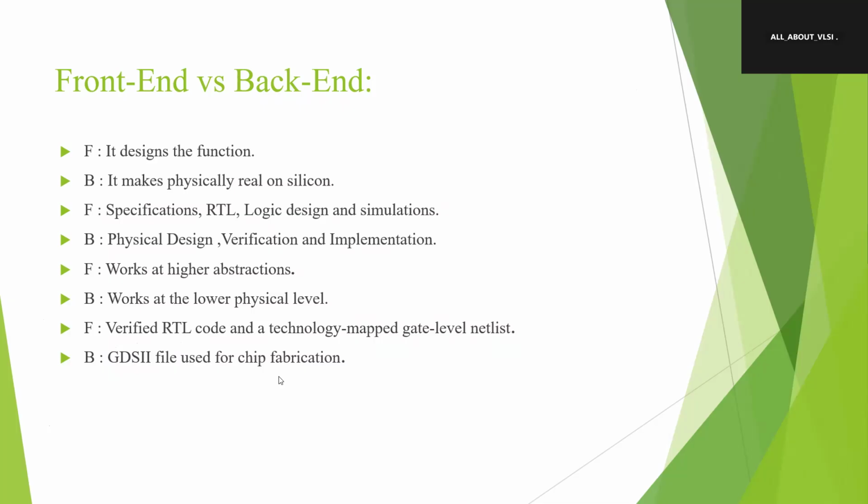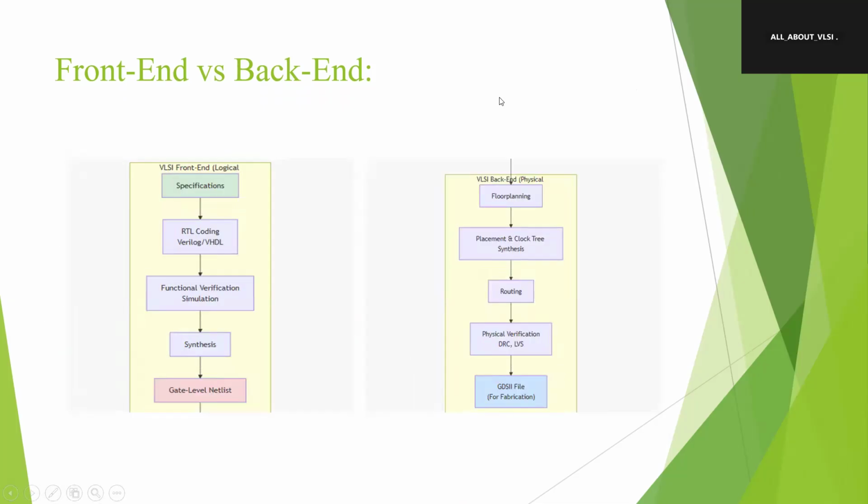So after observing this, this is the flow. First is specifications. We give specifications to that block, and RTL people write the code for that logic using Verilog and VHDL. After that, functional verification simulation is done for that logic. At the synthesis stage, what is the main purpose of synthesis?